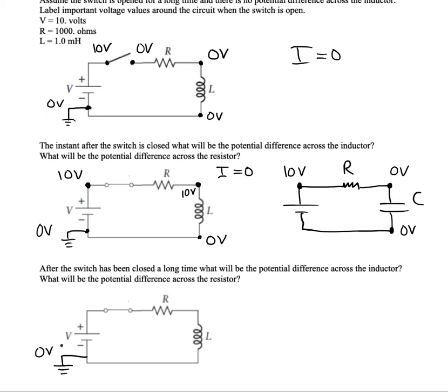All right, so we've got 0 volts at the negative terminal, 0 volts here, 10 volts here, no question about that. But how much voltage at this point now? The thing about inductors is they don't prevent current from flowing absolutely. Eventually, current is going to be allowed to flow. It just takes time to build up, though. But if it has built up, then the current will flow as normal, as if the inductor wasn't even there.